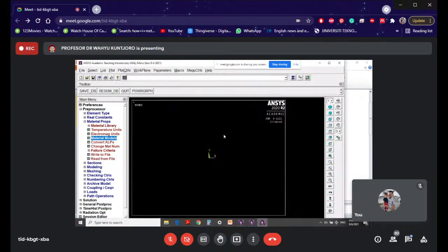What we do now is we are going to assign thickness to our element. For that, we go to sections. Normally, what you have done so far is you work with section when you want to create the cross section of the beam. Now we are going to assign thickness to our element. You go to shell, of course, lay up. Why the term lay up?